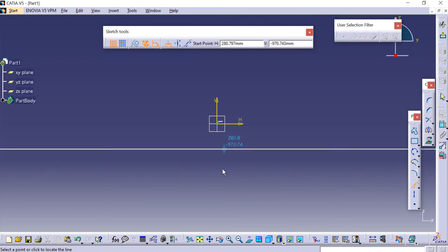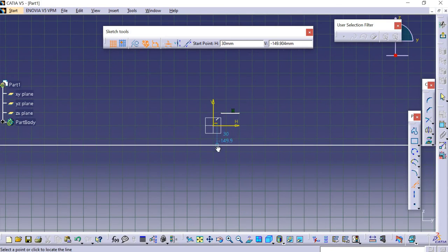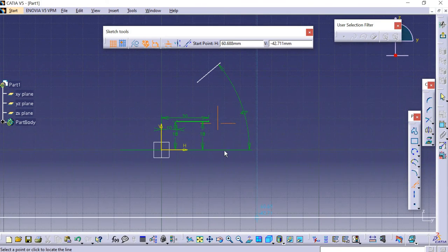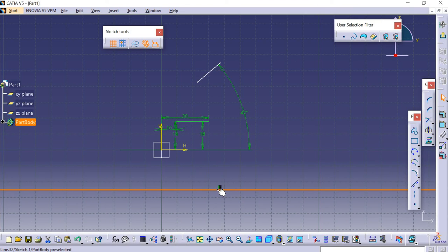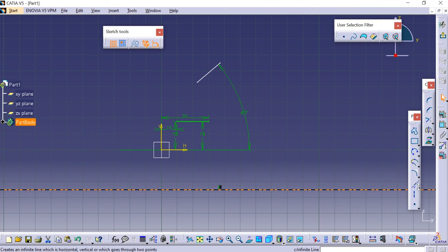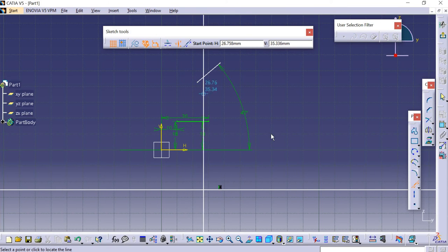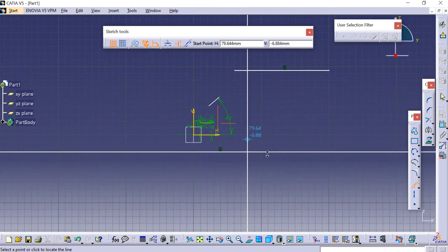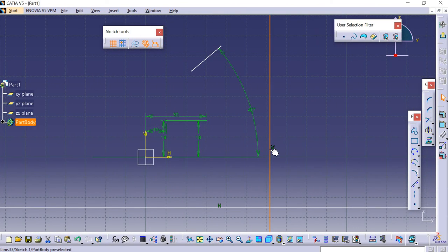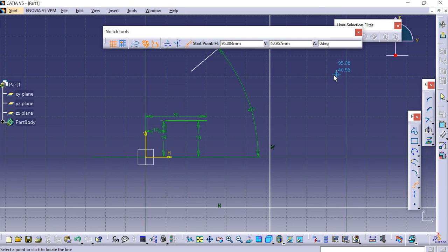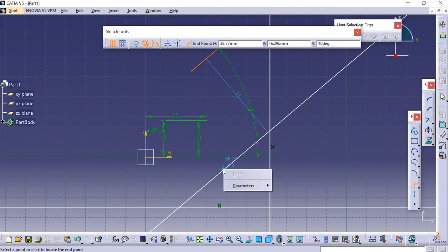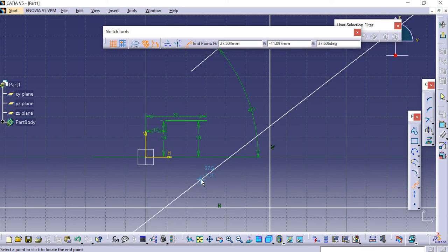Now how much ever we zoom out, we will not be able to get the dimension of the line. So this is an infinite line. And we have another option, infinite in vertical direction. Again, the same thing. And we have another option, that is slanting, which gives an angle of 25, 35, 40 according to our reference. We can draw a slanting infinite line too.